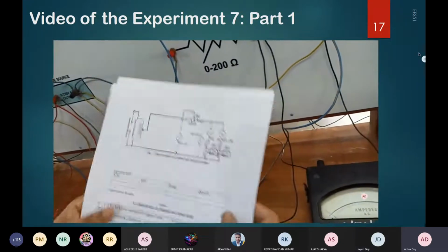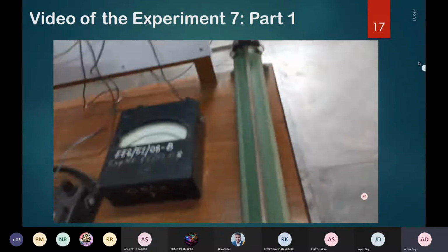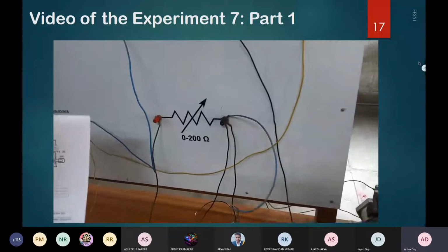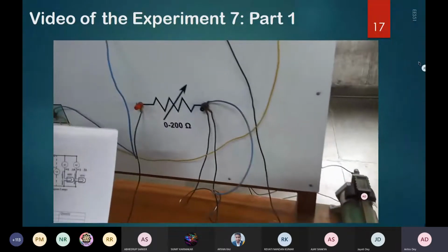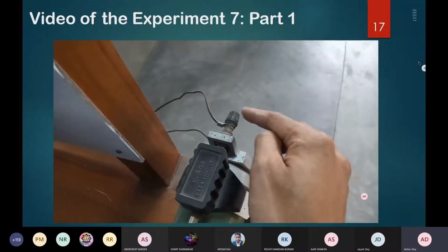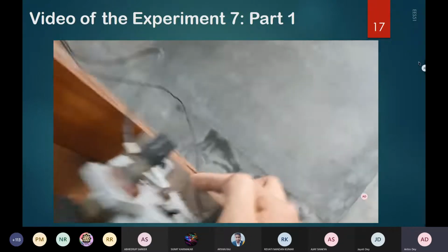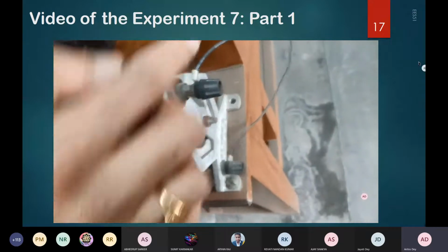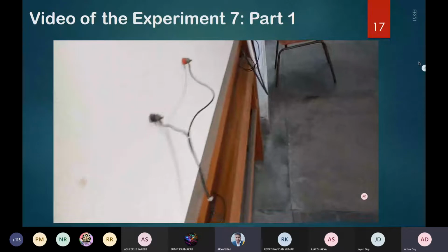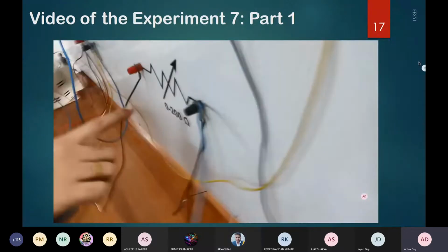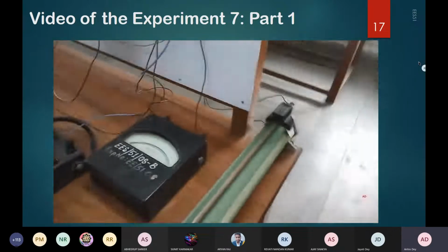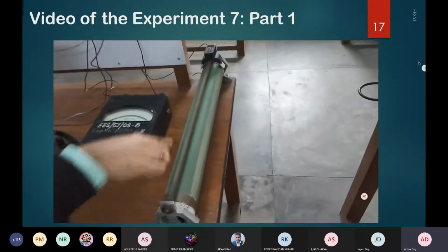So you can see from the circuit diagram, from the variac it is going towards the rheostat, which is a variable resistance. So this is your rheostat, which is shown in the panel. It is internally connected, so it has two terminals. You can see from here. Earlier also in the initial classes it was shown there are two terminals, one is here, another is there, and this is connected at the back side of this board, which you can see from the front side like this. So this is the minimum position and that is the maximum position, so you can vary between these two points.